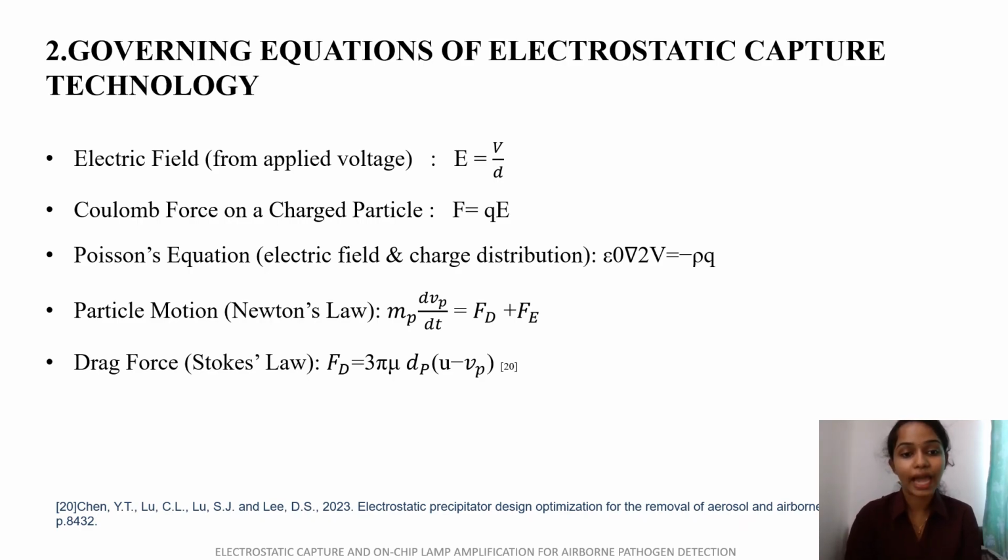And the next one is the drag force, that is Stokes law. If the drag force is too high, small particles may escape, so the airflow must be optimized. These equations tell us what voltage to apply, what spacing to use, and what airflow velocity is needed.